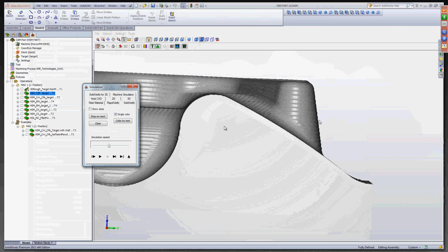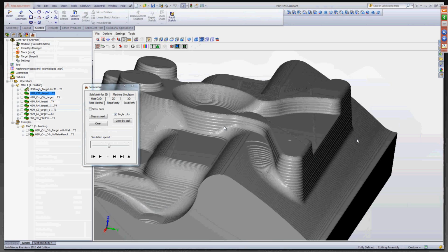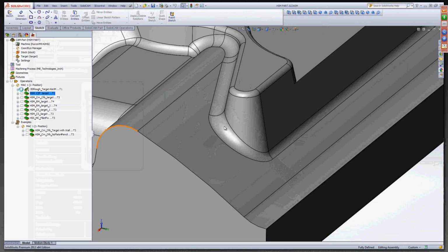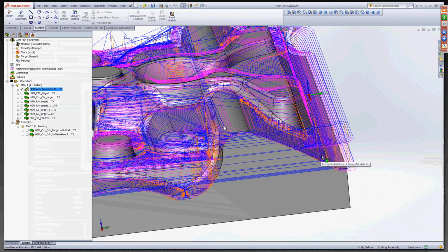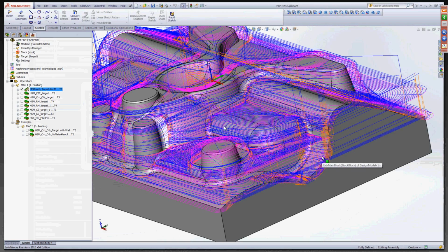And what that means is that when your finishing tool is driving across this surface, it's going to see the same amount of loading and unloading as when it's driving across this surface here. And so you don't get a difference in the surface finish based on the precondition from finishing. It's really, really a powerful functionality. And iMachining 3D does this automatically for you. You don't have to even think about it. You just tell it what the scallop height is when you go in here to the operation.